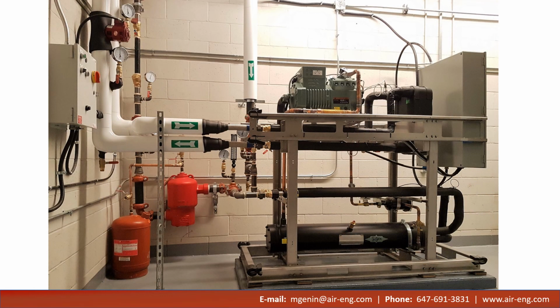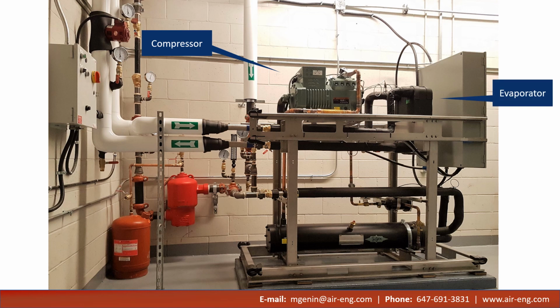This is a good example of a water-cooled chiller because most of the components are easily visible for you to see. At this point we can quickly identify the reciprocating compressor, we can identify the brazed plate evaporator, and we can identify the shell and tube condenser. We know it's a condenser because it's non-insulated. And then we can also follow the water piping here into the end of the condenser.